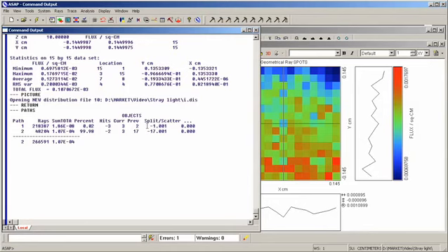So we see here that one of the paths consists of rays that were scattered from the primary mirror, object number 1. Those rays are currently on object number 3, which is the number for the detector. They were previously on object 2, which is the secondary mirror, and they saw a total of 3 objects altogether. The total power of the stray light from these rays is 1.86 times 10 to the minus 8. This is how many rays in this scattered path actually exist, and this is the fraction or percentage of the rays out of the total stray light that this path represents.